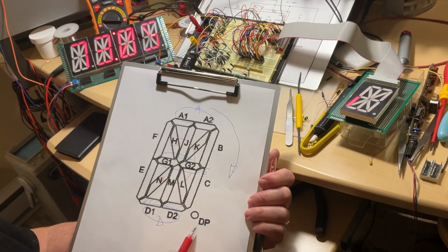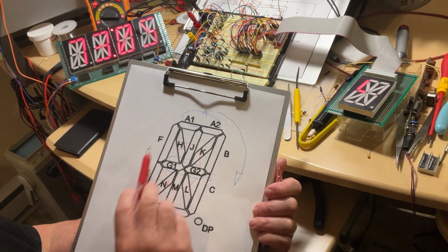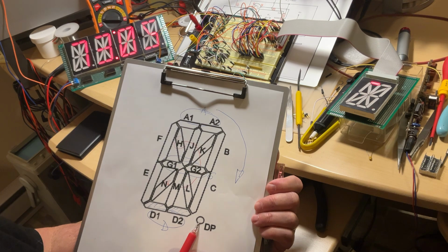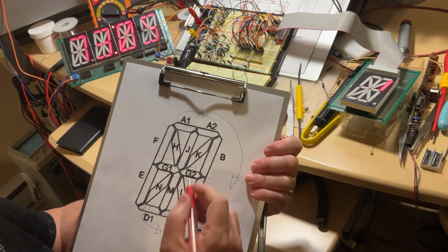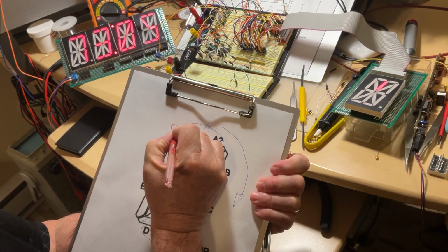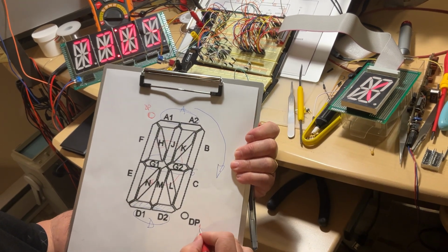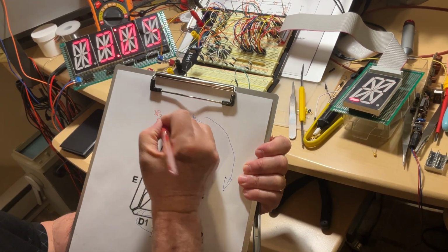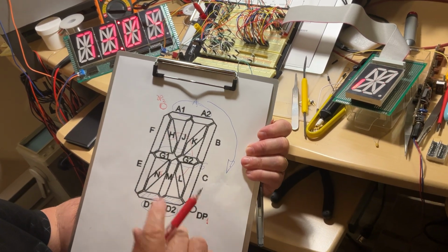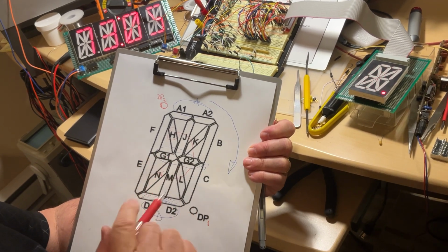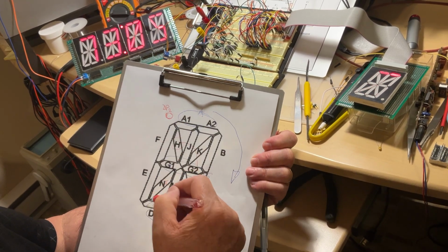And surely if we want to use the decimal point, it's separated right here. So if you count 16 segments plus this one, it's practically 17. And on some digits, you're going to find a second decimal point located right here. In that case, this one is decimal point 1 and decimal point 2. So 16 segments plus 2 other diodes here, 18. Plus remember 2 pins for the common makes 20. So that package has 20 terminals around.